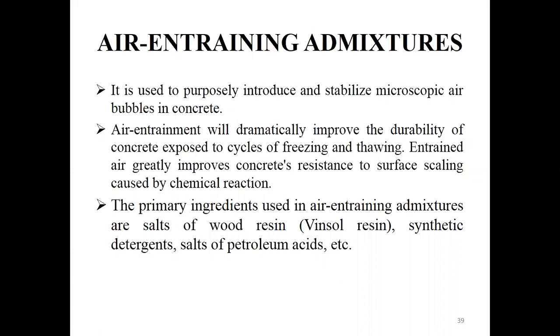In addition to these four ingredients, we will be adding one more ingredient, that is admixtures. It may be a mineral admixture or a chemical admixture. The reason for adding an admixture is to improve some of the properties of the concrete. It may be strength, or resistance to corrosion, or sometimes the admixture will be capable of reducing the freezing and thawing effect, and so on. So the reason for adding admixture is to get good properties in the concrete.